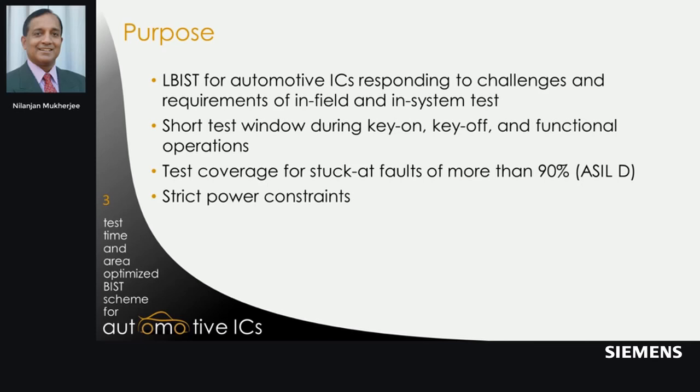Typically, logic BIST is deployed during key on and key off, and optionally when the system is in functional operation. It is critical that the tests that are run during those phases finish within an extremely short test window. It is also important that within the short test window, the defect coverage should be at least 90% in order to get an ASIL D certification.